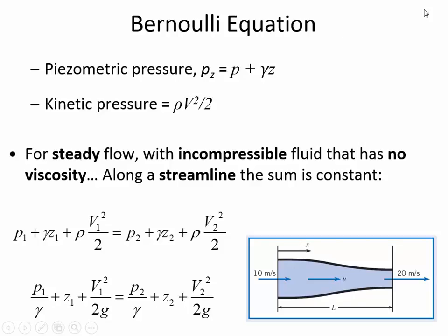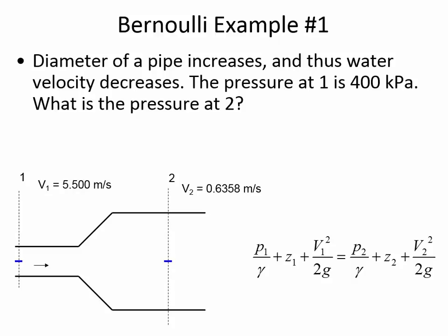Here's a diagram that we've seen before when we were talking about convective acceleration. Remember, the definition of convective acceleration is the velocity at a certain point multiplied by the velocity gradient, the change in velocity with respect to position. So du/dx multiplied by u at a certain spot. That'll give us the convective acceleration. And where the acceleration is happening the most, that's where you're having the largest or the quickest change in pressure as a result. So I'd like you to get your hands dirty with Bernoulli's equation.